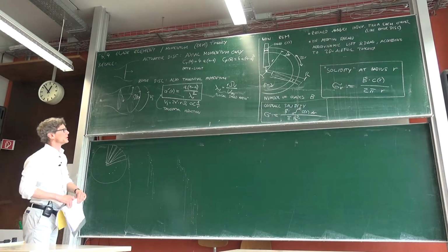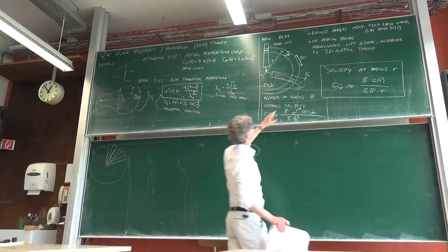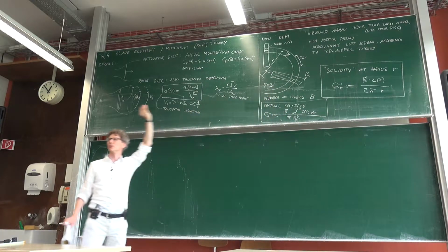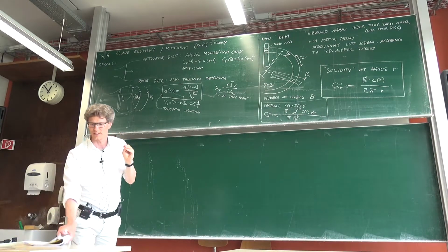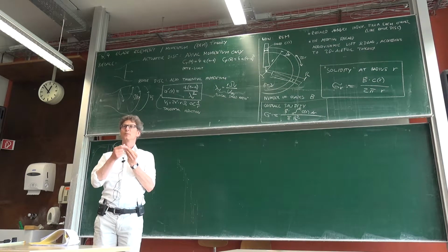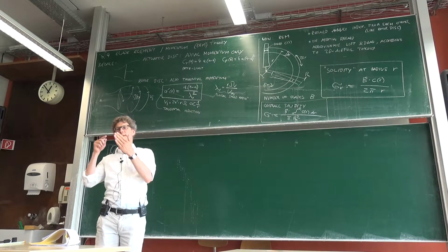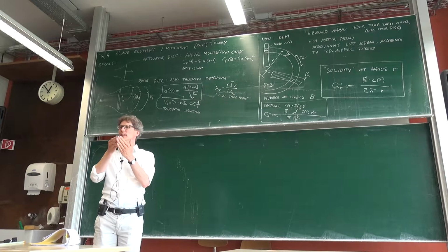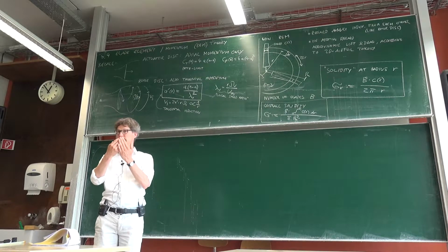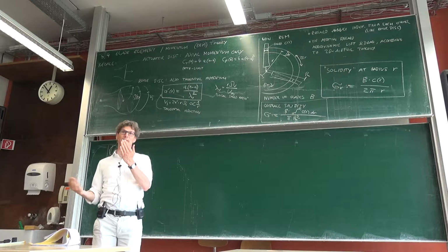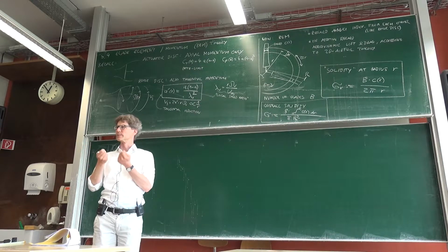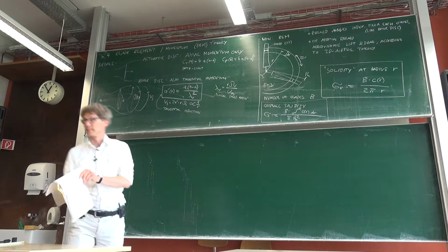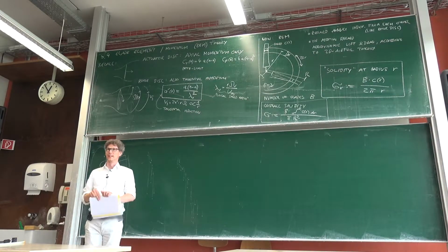Okay, so what we want to do in blade element momentum theory is we want to regard the blade element as a wing and look at local lift and drag coefficients. The problem is that if we want to compute the aerodynamic forces, we need to know not only the speed of our blade, but also exactly the induction of our wind due to our own wind turbine. So the wind will change its speed because we are there with our wind turbine, but our forces will depend on the wind speed. So there is some coupling, right? It's interdependent, and it will lead to implicit equations that are not so easy to resolve. But it's allowed and necessary to collect everything that we know about it.